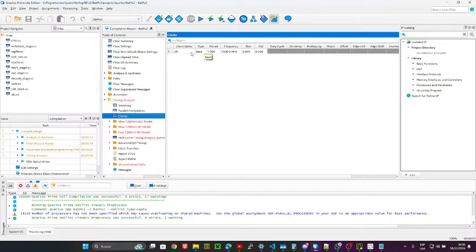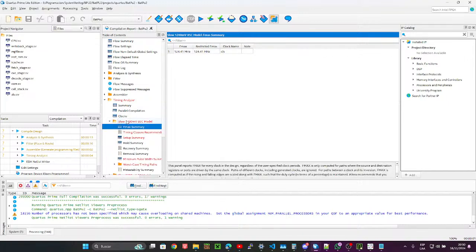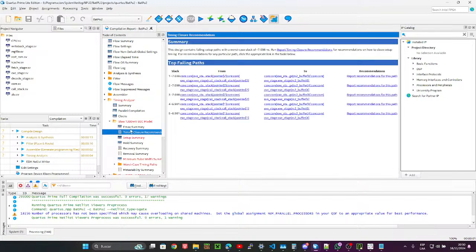That's called feedback. So you take the output and you bring it back to the input. If you connect the output directly to the input, that causes the PLL to output whatever frequency you give it on the second input. If you put a divider, like a D flip-flop, on the feedback, then you give it, say, 1 megahertz input.